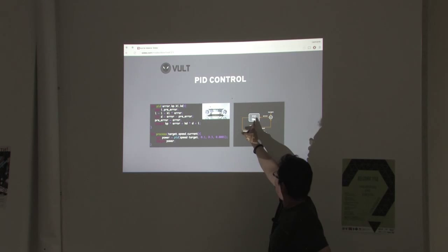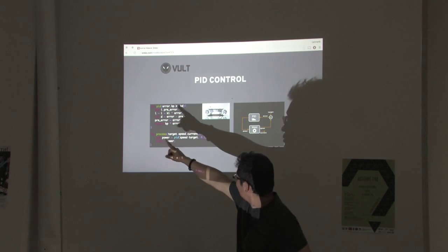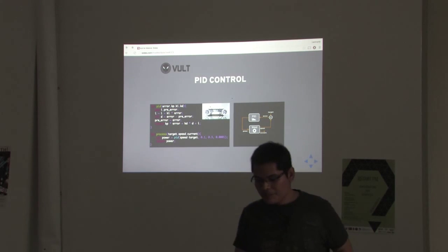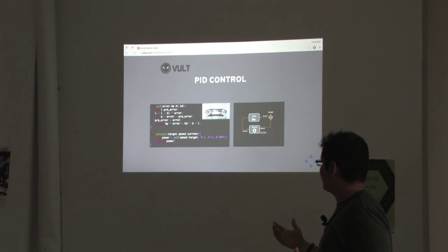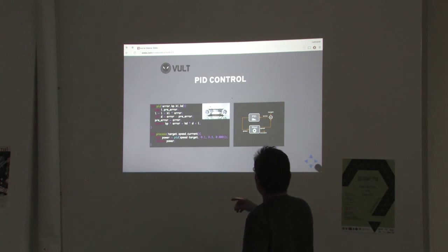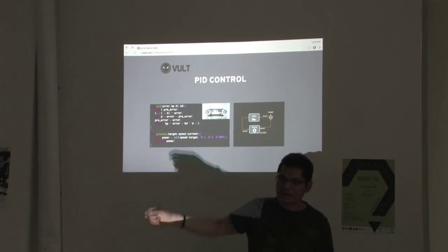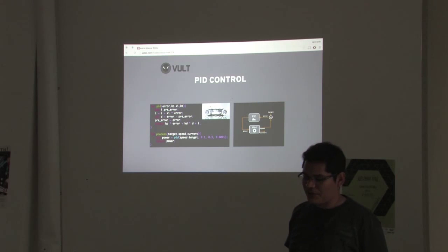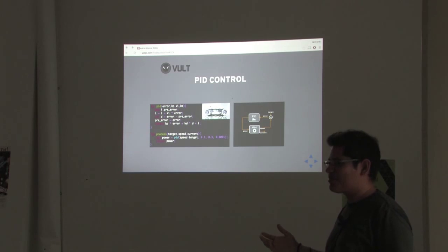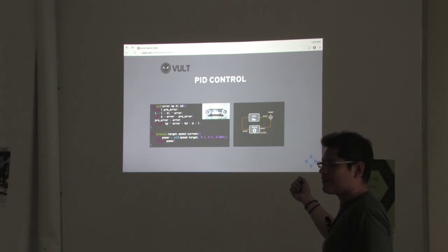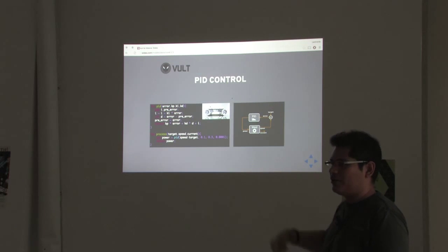And then you can put that into a PID controller, which is the source code of a typical PID controller, which internally is a function with context. But once you have this PID controller library, you create that function. Once you have that function, you practically have the power to control a lot of things, because you just need to provide the coefficients. And if you are doing another application, you just import this function and call it again.